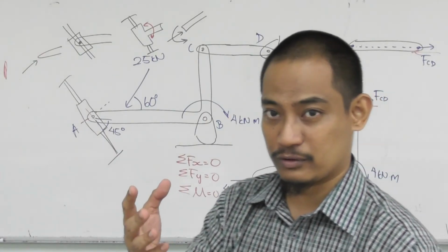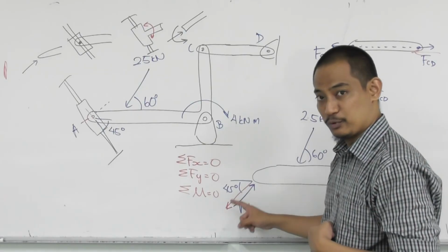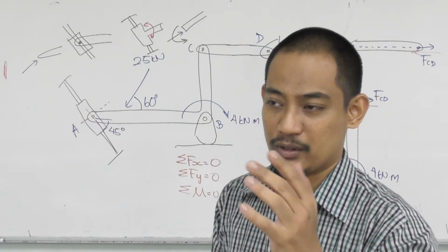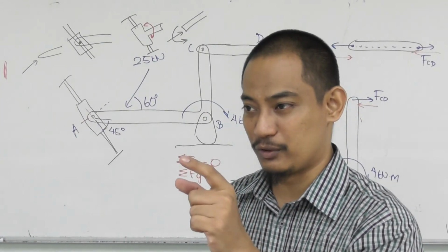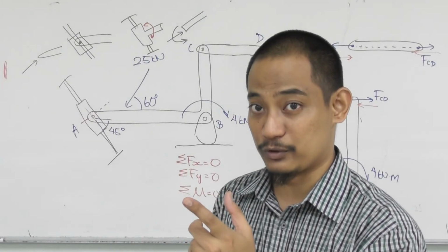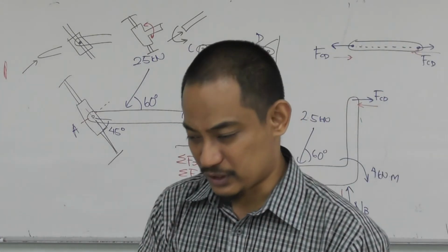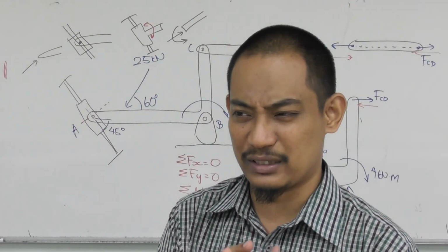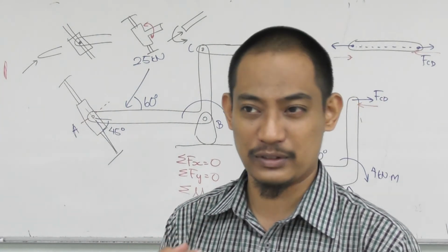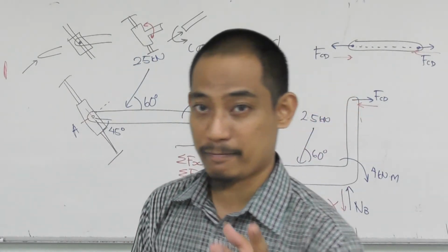But if you do not draw, because for example like this, it can go both ways. Without the drawing, we cannot know which direction you assumed. Hence, we cannot know whether your equation is correct or not, right? So that's why it's important. Similarly here, without the free body diagram, your equation doesn't carry any meaning. We do not know whether it's a mistake or whether it's correct, etc. So that's why you have to have the free body diagram.